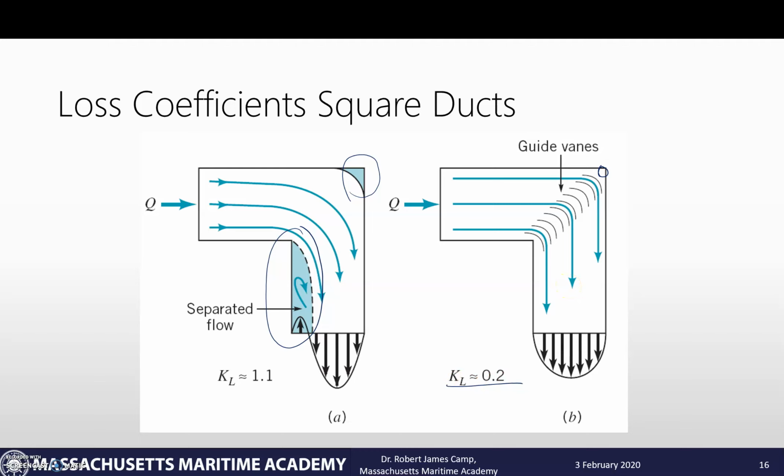So this is all that minor losses are. We just add them into our system just as we've been using them, but now that gives us that last little component of our energy equation. So we can find the major losses, add to that the minor losses, and then go about solving the equation for what we need from the piping system.